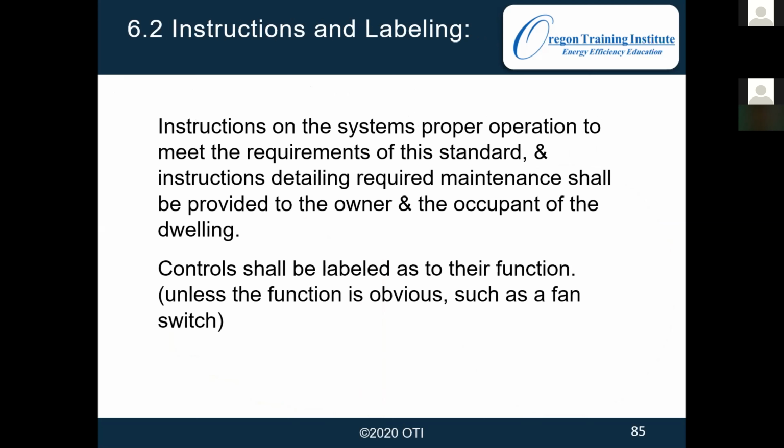When we install the ASHRAE fan and set it up, we want to make sure that it is labeled, how to turn it on, or what the switch that operates it is for. Since the fan is mostly silent, the homeowner might flip the switch and not realize it does anything and could end up turning it off when it needs to be on.